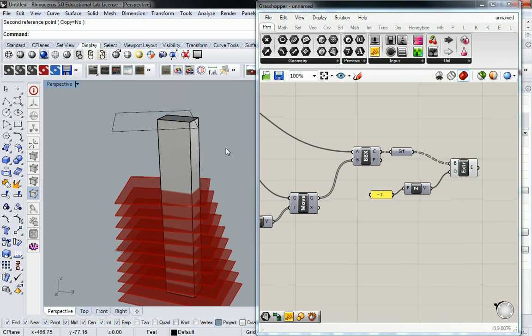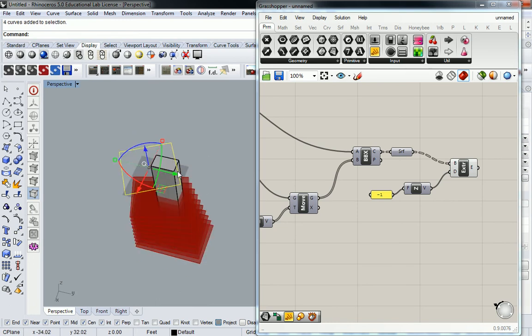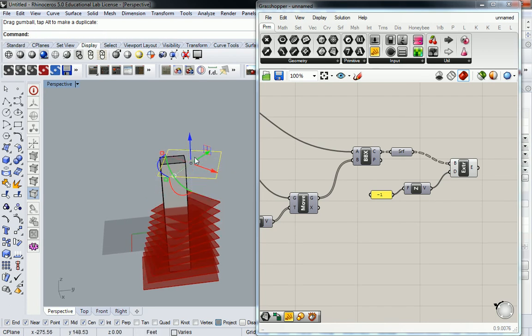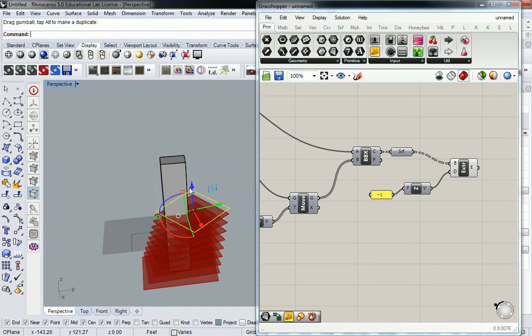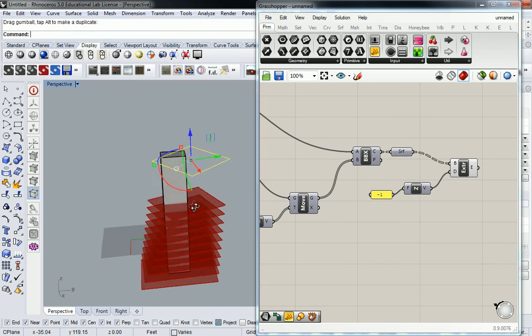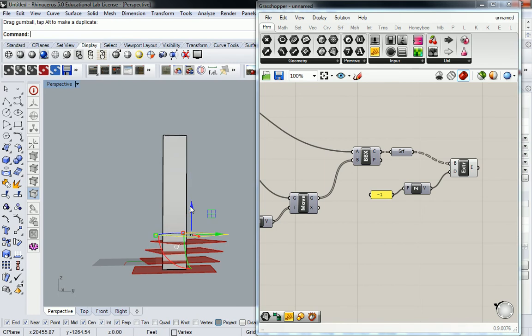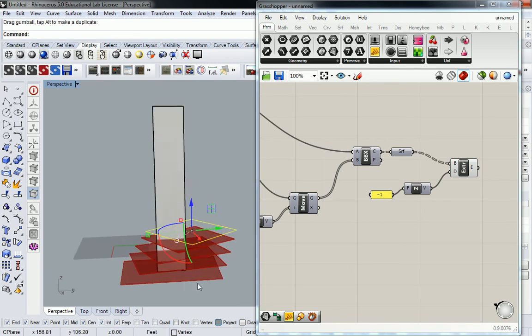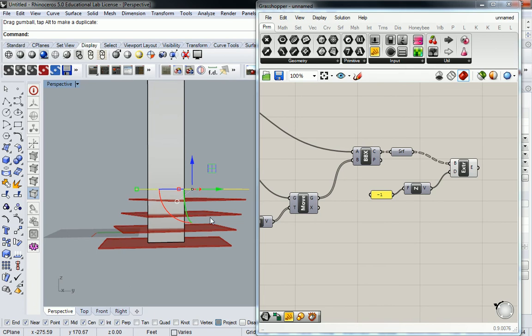Okay, so what's great about this is that now, as a designer, I have complete fluidity over my skyscraper. In this case, it's more like a mid-rise, but I can very fluidly just grab this thing and yank it off to the side. I can twist it a little bit more. I can twist it a little bit less. Raising it up and down won't really change much except for the location of the volume. And notice here, when I pull it down, the number of floors just modifies to account for how many were there before the volume stopped. Does that make sense?